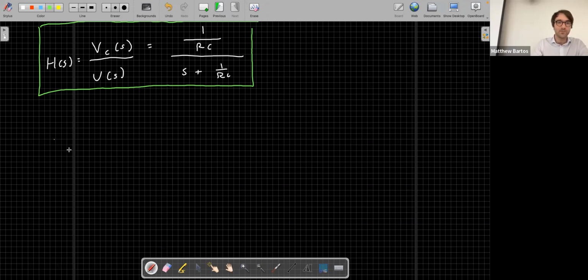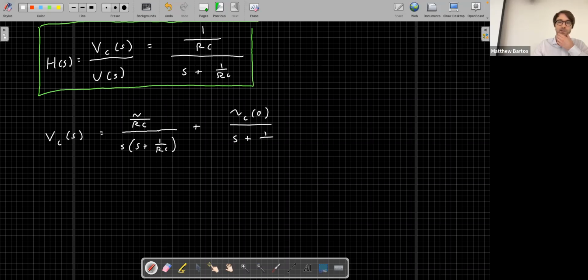So we have Vc of s is equal to V over RC over s times s plus 1 over RC, plus Vc of 0 over s plus 1 over RC.